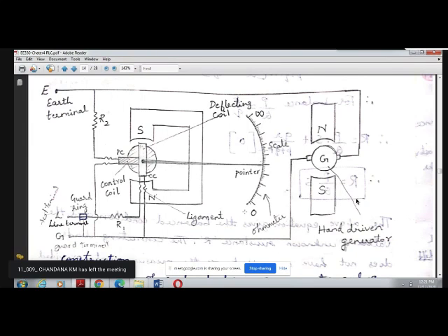Once these two conditions are satisfied, then you connect the insulation cable whose resistance has to be measured across the terminals L and E, that is the earth terminal and the line terminal. Then again start rotating the generator handle, the pointer will come to rest at the point which is the value of the resistance. So this is how a megger will work.